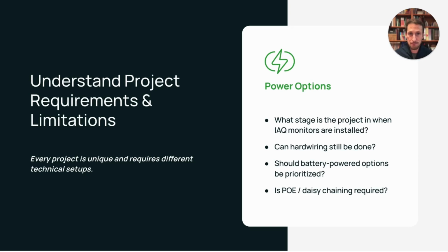or battery power. And the right one for you depends on what stage the project is at, usually. So if you have a new build, then hardwiring is generally quite simple. During construction, you can make sure that there are cables available, and it will be very simple to configure and get that monitor connected and online.